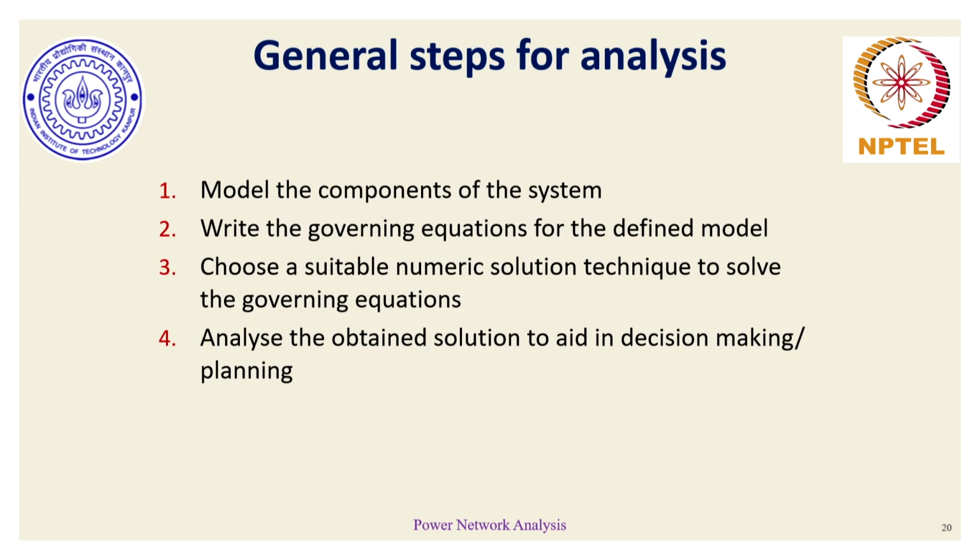So to summarize, if I have to analyze a given network at different time frames, I would first figure out what the components of the system are and how to model them appropriately, so that the model represents either the steady state, the transient state or the subtransient state of the network. So system modeling is the first important step.